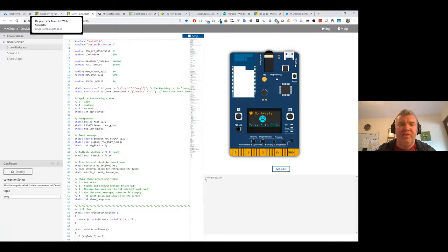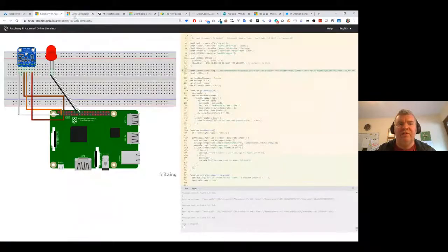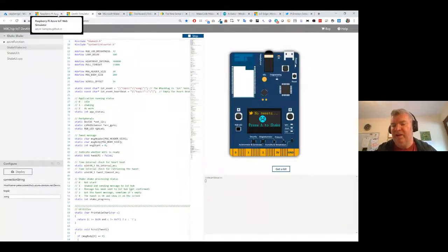And they're the two main simulators that I tend to use when I'm talking about Azure, just because it's so fast to get started and you don't need to delve too much into the code. But when you do start coding, we mentioned earlier, you can do that in a plethora of different languages. But one of the ones I've been demonstrating recently is C#. So .NET Core you can get installed. It's not particularly straightforward to get .NET Core installed on a Raspberry Pi. If you've got a 64-bit, say Ubuntu or something, then there's a sudo apt-get for it, which is nice. But on a Raspberry Pi, it's a 32-bit ARM system, and there's no apt-get for the 32-bit binaries, sadly.